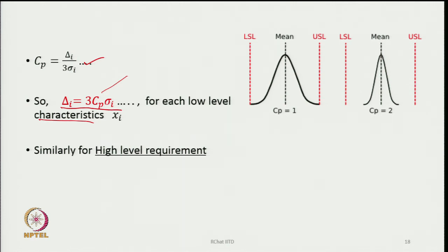So, if my customer asks that I need a product where the Cv will be 5%, and I know that my process can only give at the most 10%, we should say that the process is not capable. There is no point in taking that order and trying to execute it, because we will fail since the process is not capable. So, we must understand the capability of a process. Whether it is a spinning process, weaving process or garment manufacturing process, whatever process it is, we must have an idea of the capability of the process.